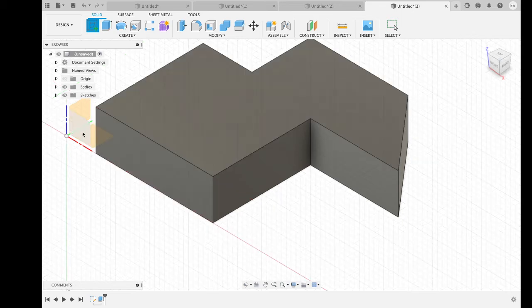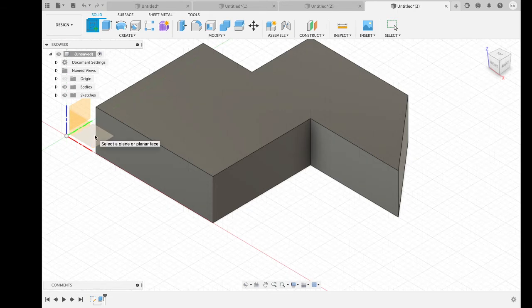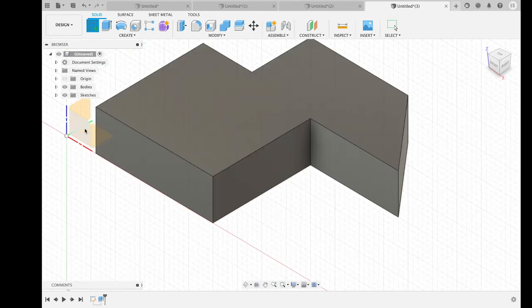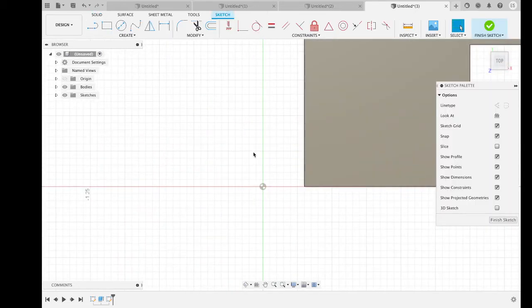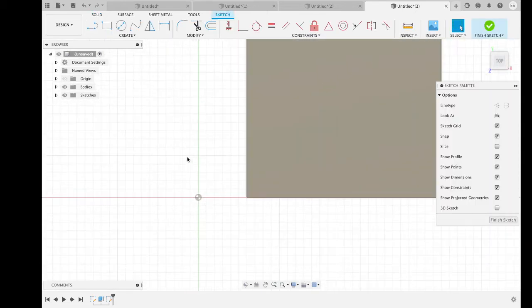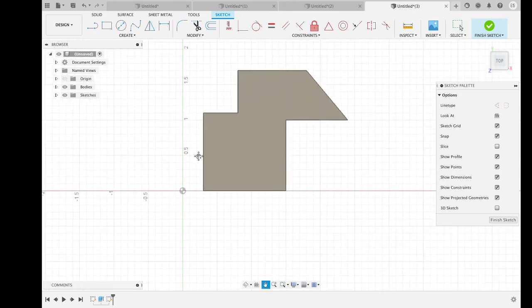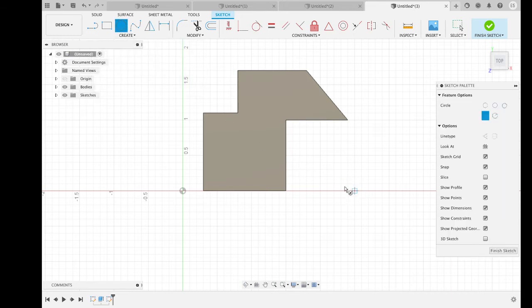Okay. So I'm gonna add one more sketch here. Click, and then you're adding a new sketch. Because I created a new sketch, this one is different from the sketch I previously selected. So we are creating a new sketch. Okay, so let's use this one, circle, and circle is also similar. You can select a center point and extend the mouse, and then you can draw a circle.